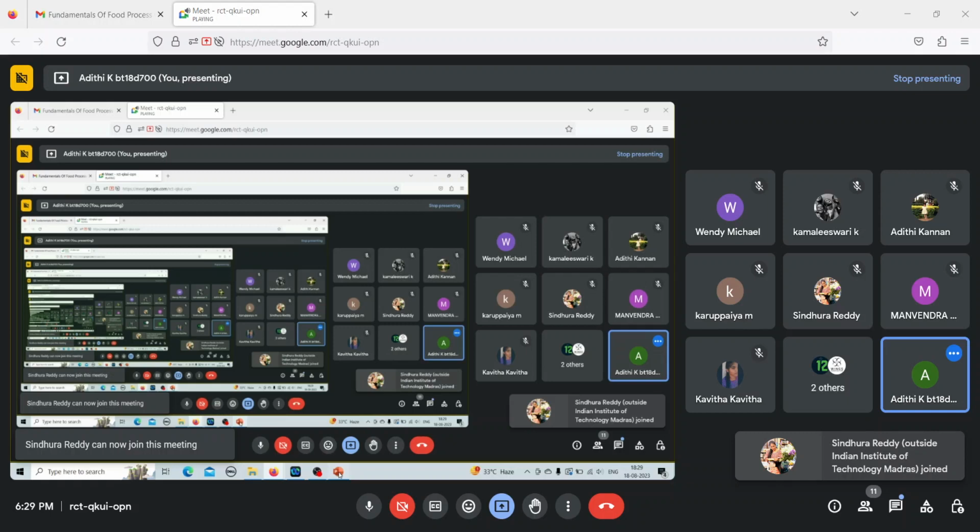A is the area of the evaporator that is asked in the question. Delta T is the temperature difference between the steam and your feed and your liquid. So in this case, we already know Q. U is given in the question. We need to find the area. We can find delta T, which is the temperature difference between the steam and your liquid.